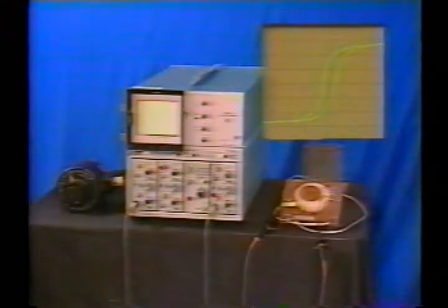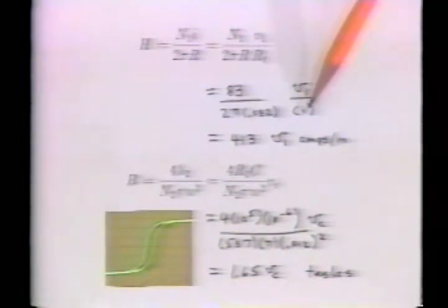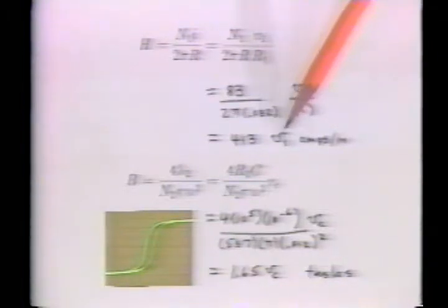The minor diameter of the secondary coil is 1.2 centimeters. There are 537 turns. The integrating circuit has resistance 100 k ohms and capacitance 1 microfarad. The scaling factor relating integrating capacitive voltage V sub C to magnetic flux density B is 1.65. With a vertical scale of 0.5 volt per centimeter, each vertical deflection of 1 centimeter is 0.83 teslas. Thus, for this core, saturation is reached at B approximately 2 teslas for an H field of about 500 amps per meter.